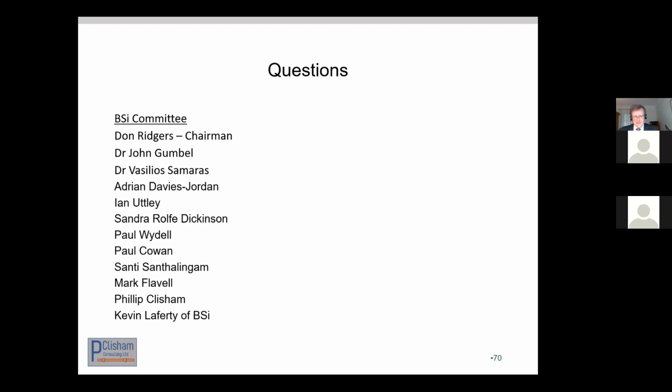We've now got a comment from one of your fellow BSI committee members, Sandra Roth Dickinson, who you actually mentioned in your presentation. Good afternoon, Sandra. So she says, a great presentation, Phil. I think it's worth noting that whilst the Gumbel method is currently to be applied to large diameter plastic pipe, it is the intention in time to ultimately widen its application to all pipe materials and sizes. And Sandra's spot on, and that's definitely the intention. It's a better model, and we just want to gain confidence and get feedback from its use in this version of the standard, so we can broaden its use hopefully in the next edition of it.